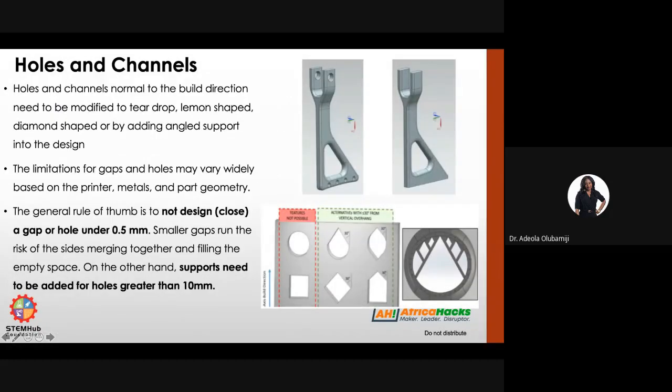Also, there are a couple of things. This is very specific to laser powder bed fusion, though; not all the technologies require this. For laser powder bed fusion, it is very angle specific. If your overhang angle is less than 45 degrees, you will need support structure. So in a lot of cases, we try to orient our parts such that there is a greater than 45 degree angle when you put the part on the plate.